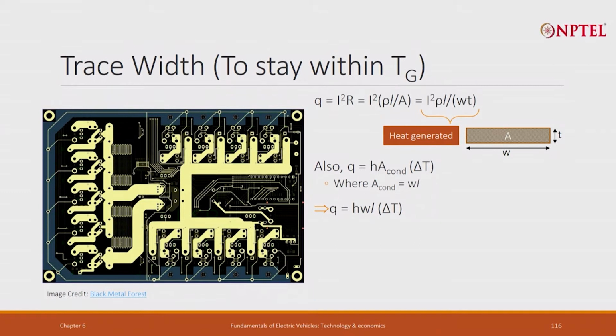Interface means when two objects are in contact, and that multiplied by the area available for conduction into the temperature difference between the two surfaces that are in contact, the junction temperature difference.